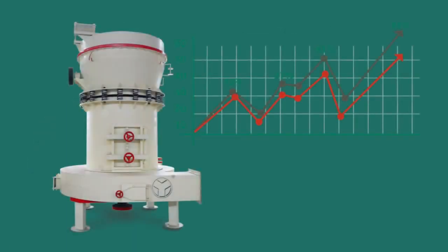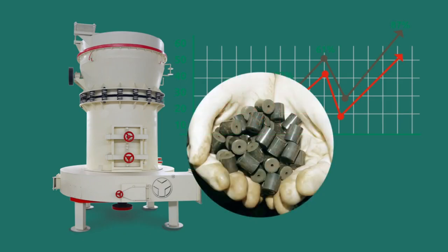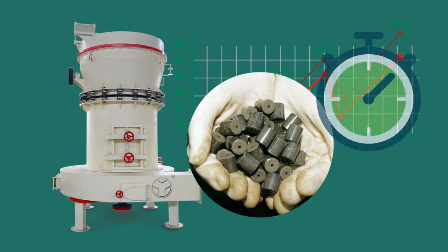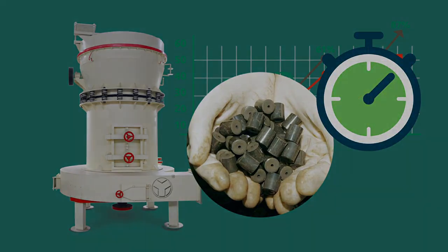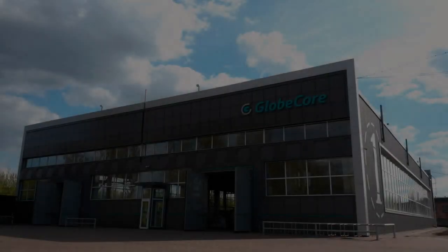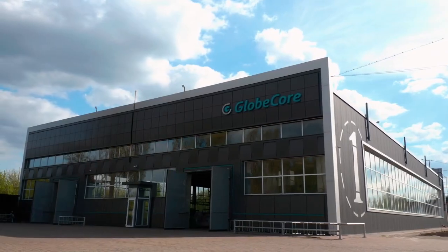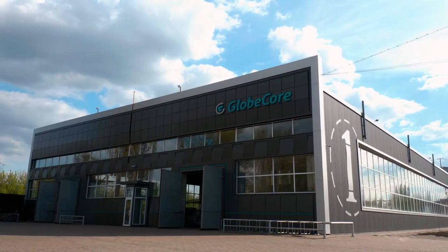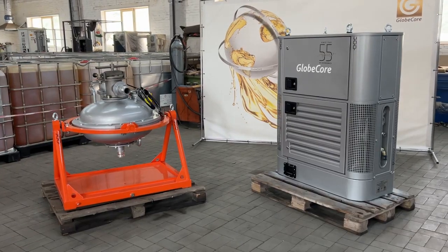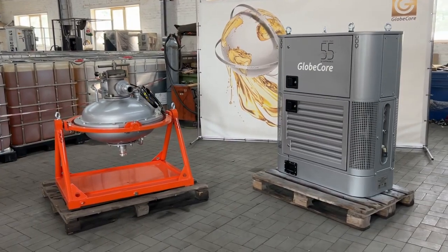However, such mills prove to be low efficient in pulverizing and mixing the initial powders. Therefore, after the pellets have been sintered, a clear separation of 2 phases can be observed, which indicates the lack of required homogeneity. In addition, the actual process is time-consuming and takes from several to dozens of hours. Thus, Globecore has developed an alternative innovative technology for producing MOX-fuel for nuclear reactors based on Vortex layer devices.